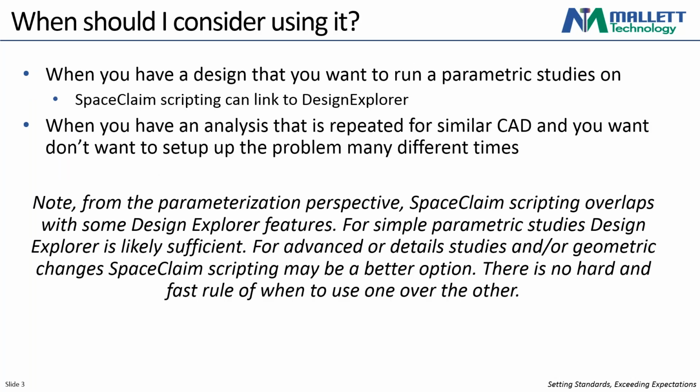So the next question is, when should I consider using SpaceClaim scripting? In all honesty, it's not a cut and dry decision. I think the first criterion would be, is there a need to run parametric design studies and/or a need to run analyses on similar geometry over a range of cases? That could be a reason to look into SpaceClaim scripting.